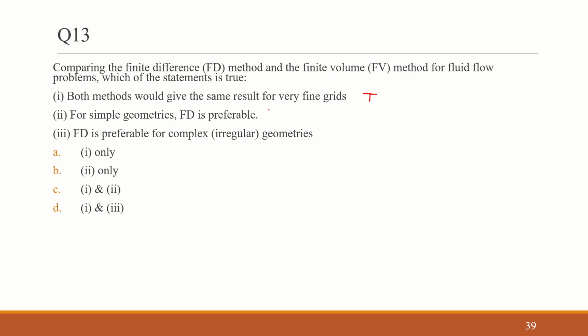For simple geometries, FD is preferable. Again, this is true. FD is preferable for complex geometries. This is false, because in complex geometries we would not be able to use FD directly; it would be complex to use the FD method for complex geometries. Rather, the finite volume approach would suit better. So the answer is 1 and 2 are right, which is given in option C. Option C, 1 and 2 is right.